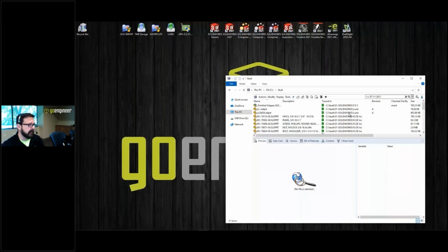Now, those of you that have played around with the full-blown search tool in SOLIDWORKS PDM, you can go to that search tool and you can add multiple variables and logical operators like contains or does not contain. But with this little quick search, put in a portion of a part number and then the operator, all uppercase, like you saw me do, and then a space and another part of a description, like it's going to have the word cover in it, or it's going to have the word door or something like that.